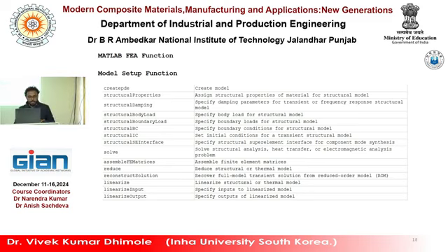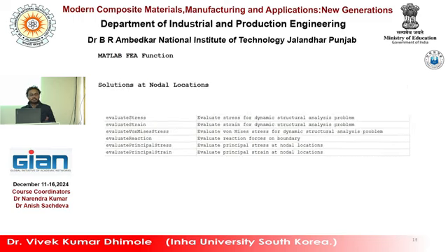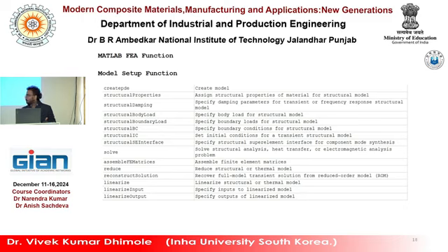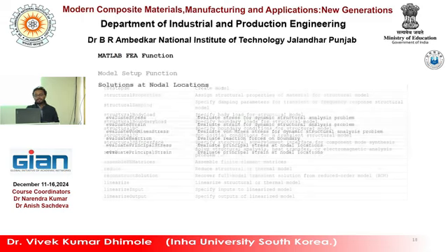Normally, when you go to solution one, evaluateStress is a function that gives the stress solution. evaluateStrain will give you the strain solution. evaluateVonMisesStress will give you the von Mises stress solution. reactions will give you the reaction solution. So these functions will give you the model setup, meshing setup, and analysis setup. These are functions in MATLAB you can use directly for this purpose.